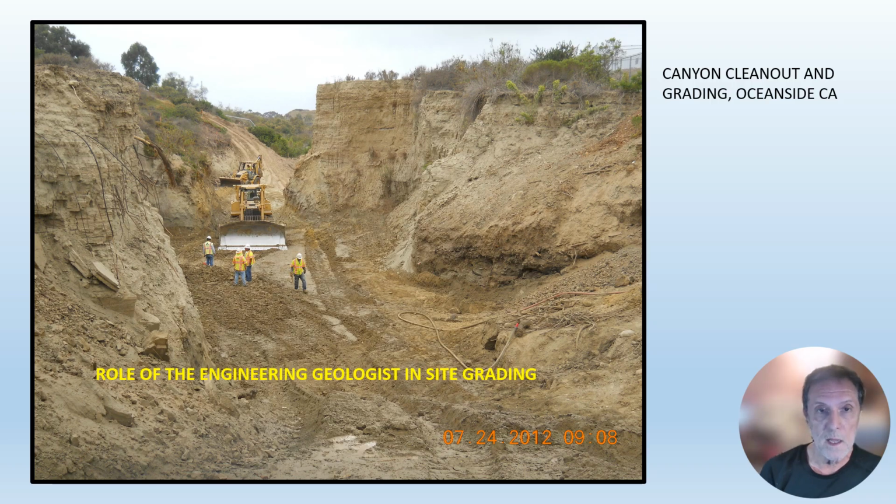So here is a picture of a canyon cleanout in the city of Oceanside near a school. You can see here in these layered silts, this was an old pond fill full of silts that had to be removed. And so the canyon had to be dug out, excavated, and replaced with more suitable material.